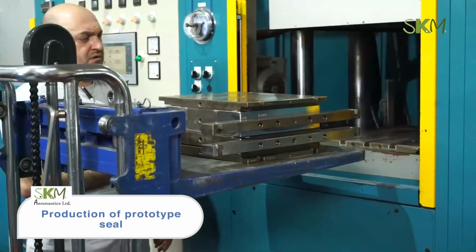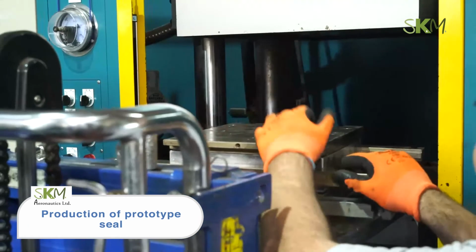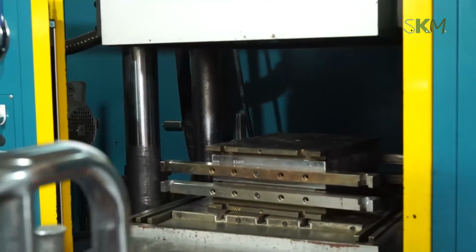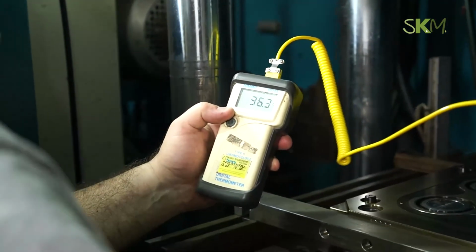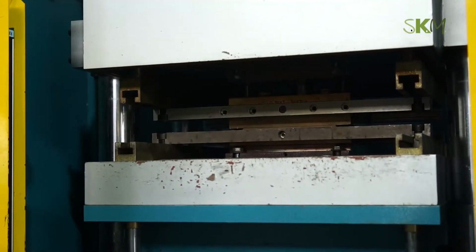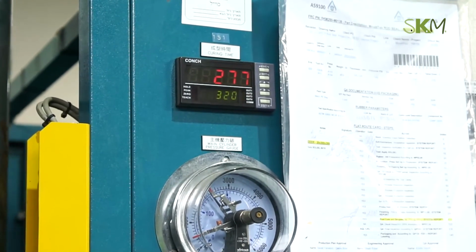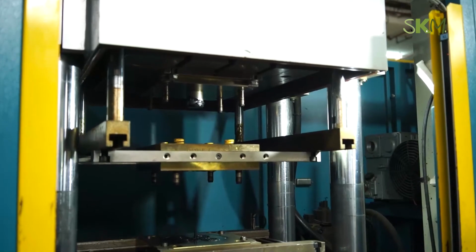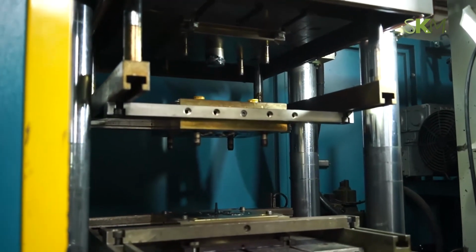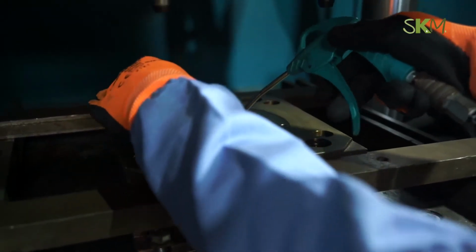The prototype tool is prepared for the molding stage and set in the press. Its temperature is checked to verify that all operating conditions are met. Rubber is weighed and placed inside our prototype mold to be molded into our prototype seals with their defined surface texture. Its release is helped by pressured air.